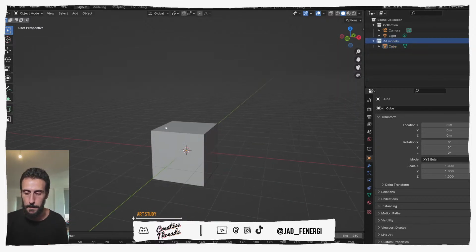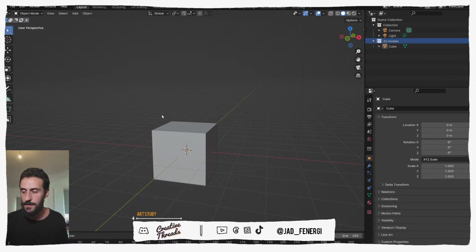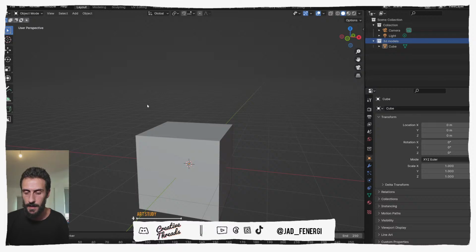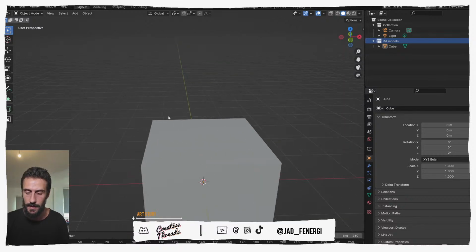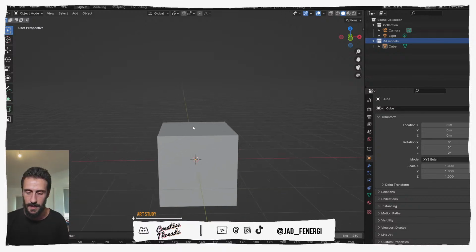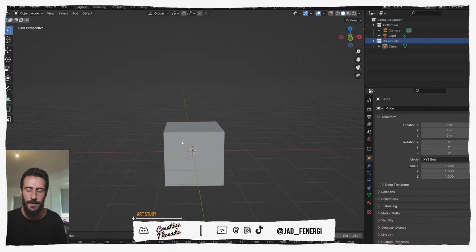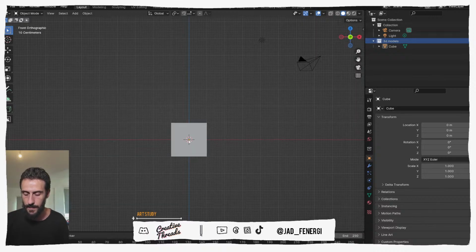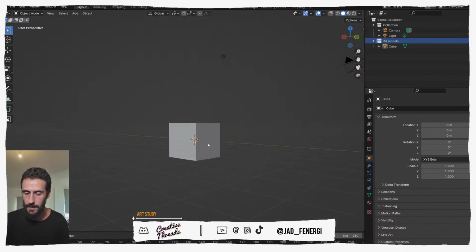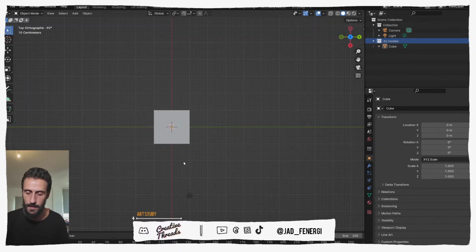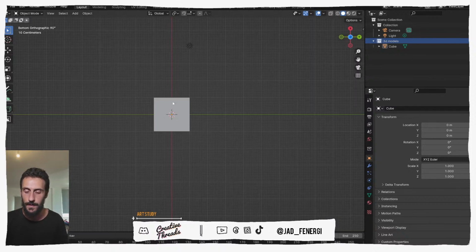Okay, so there are lots of things to learn about Blender. I'm not gonna go through all of them. I'm just gonna go quickly through the viewport first. So middle mouse to turn, scrolling to zoom in and out, and Ctrl and middle mouse you can also zoom in and out. If you have a pen, you could do it. You can do some different keying. And if you press Alt while rotating, you're gonna snap into different corners of the viewport, like top view, or front view, or bottom view.